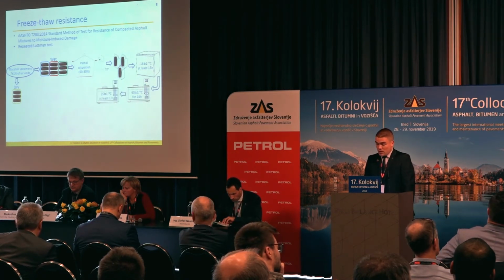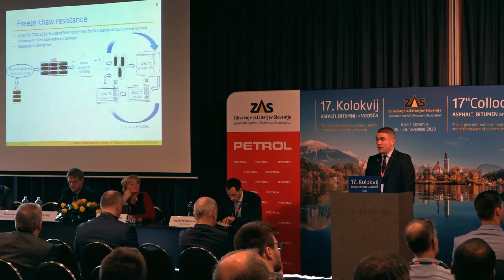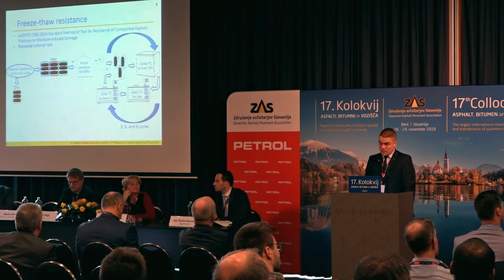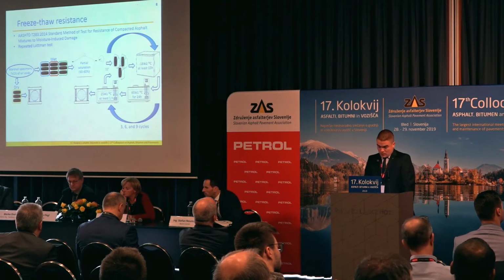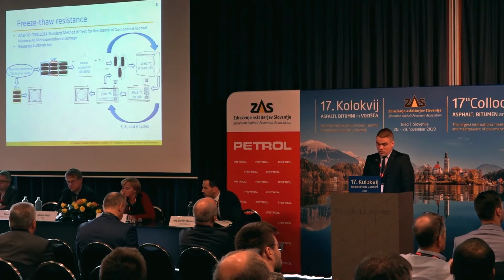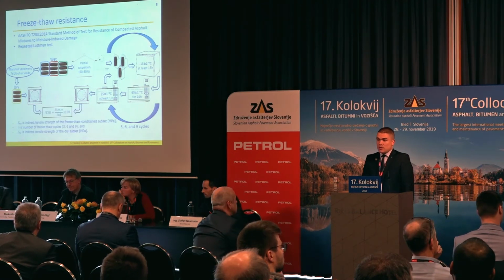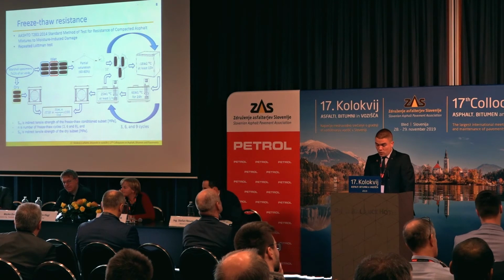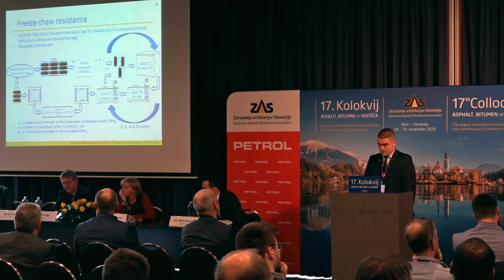After that, they were immersed in water at 25 degrees for at least 1 hour, and this procedure was repeated 3, 6, and 9 times. After these cycles, ITS values of all subsets were determined, and the measure of freeze-thaw resistance was defined as the ratio of conditioned subsets and unconditioned subsets.